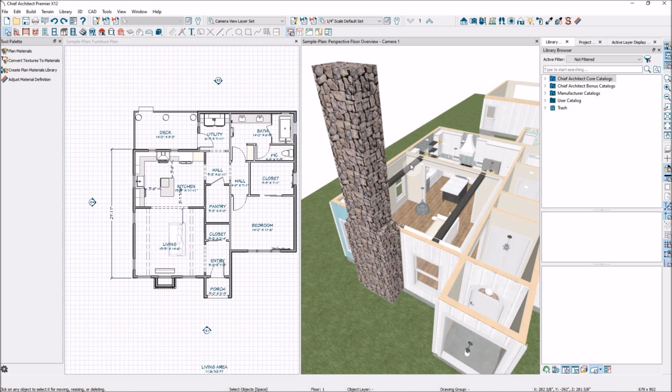So you could end up with conflicting textures. So if you are doing rendering and you're getting some sort of flickering or something like that, it's because you've painted over something and there's two different textures attached to that object. So again, that's where it's going to be important to always do a purge and go through the dialog box of the object and check those materials when you can to make sure that they are linked properly.